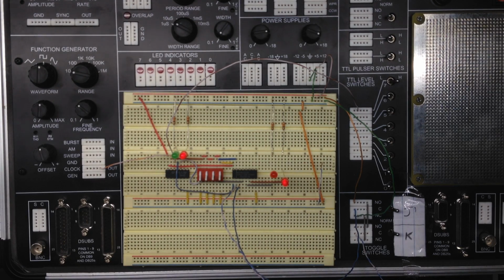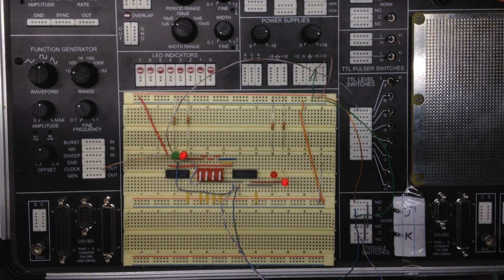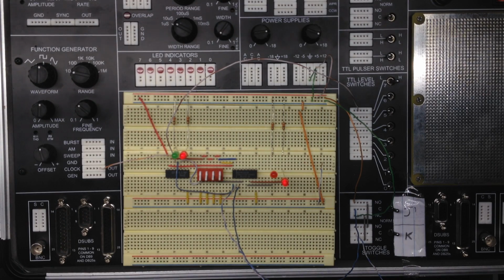The other portion of the logic table for the 112 IC that we're going to take a look at is the preset and the clear functions and how they operate. In the truth table, we see X's under clock, J and K for any time that either the preset or the clear is low. The reason that happens is because the inputs on the clock, J and K are all ignored whenever either the preset or the clear receives a low signal.